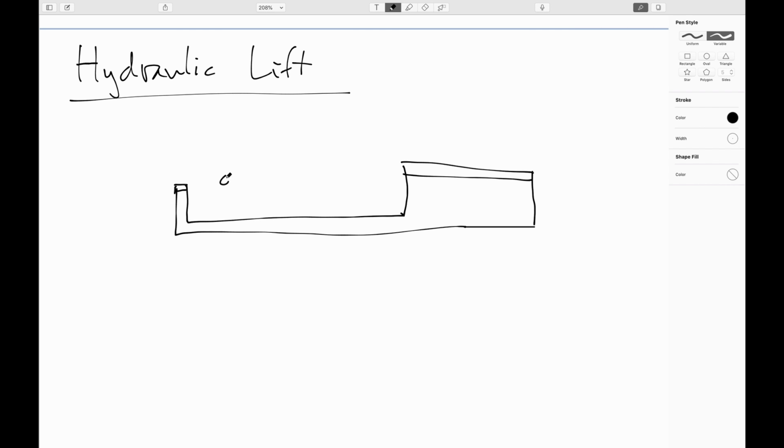And then usually you've even taken a step further and you've rigged up some sort of a lever here so that you push down on the lever to make it easier to push down. And as you push down on the lever, like so, the pressure here is going to go up because you've literally increased the force being applied here, and the area is not changing.